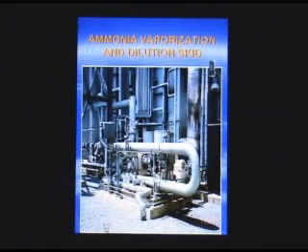Another example of just an ammonia dilution skid. One of the big issues on SCRs is you need to have uniform flow into the grid. In some cases, they will use CFD modeling depending on the hot gas path flowing into the grid.